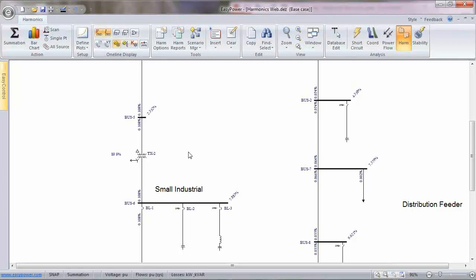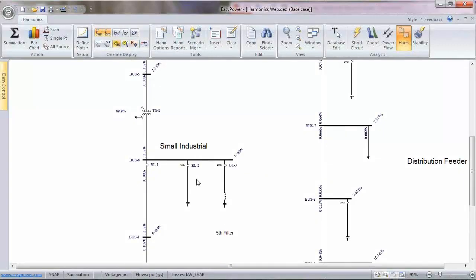What if someone incorrectly decided to put some power factor correction on here, thinking they were doing us a favor, and we added the power factor correction capacitor on. Because this produces a resonant condition, we see that we have a high voltage distortion and the derating drops like a rock, which means now you can only put 67%.